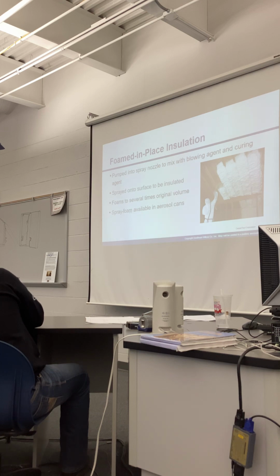So you go in and you spray 1 inch of foam, so you get R7 out of that 1 inch, because foam insulation is R7 per inch. So we get R7 out of 1 inch, where R13 is 4 inches, right?